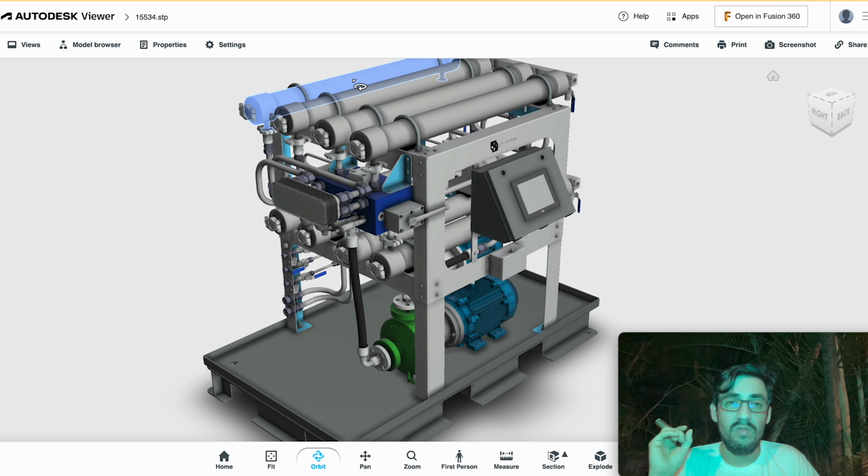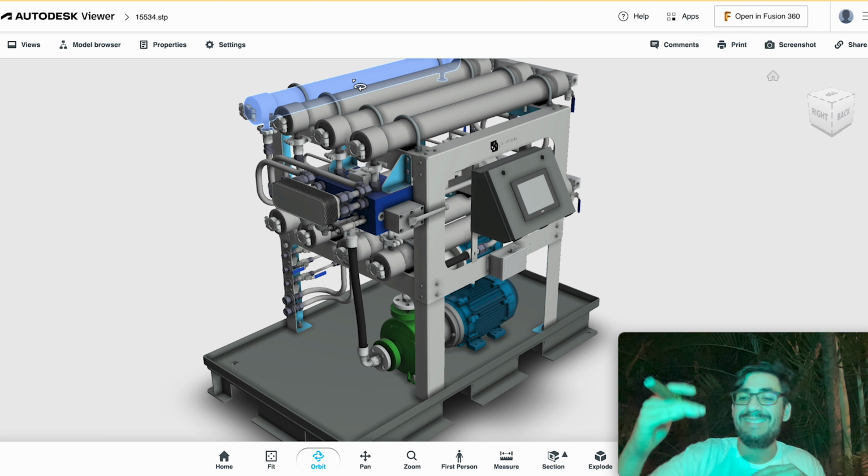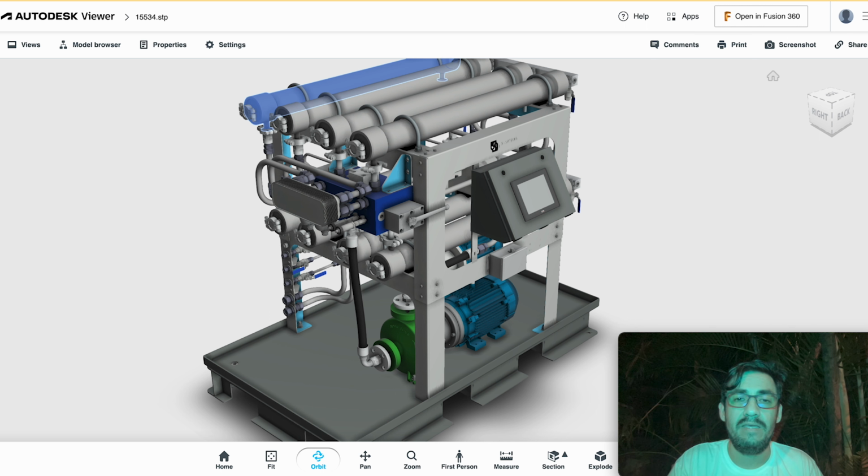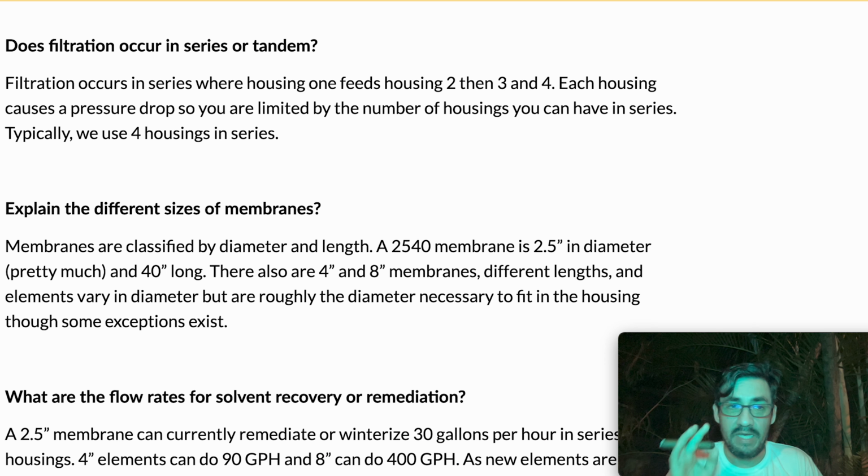And so the fourth membrane is not going to permeate as good as the first membrane because you don't have the pressure. And so they would not be compatible if your next step was like a higher pressure application. So that's why you can't have that duplex functionality in series, right? But they do function in series.